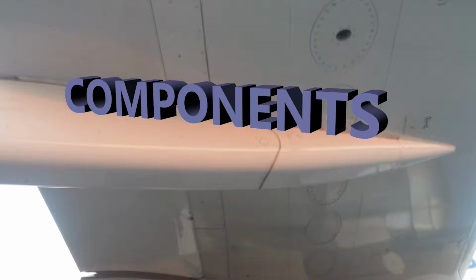The shorting and fuse plug connectors, like I mentioned before, remember I said how you have those in the wings and then wing and center tank for the fuse plug connectors. Well, here's what you have. You had them on the wire, installed between the external wiring harness and also the in-tank wiring harness. So that's where those connectors are located. And those are all behind the access panel, and I'll just let you follow your AMM as far as exact location. And those connectors are just connecting what? External to in-tank wiring. So it's connecting those two wiring harnesses.